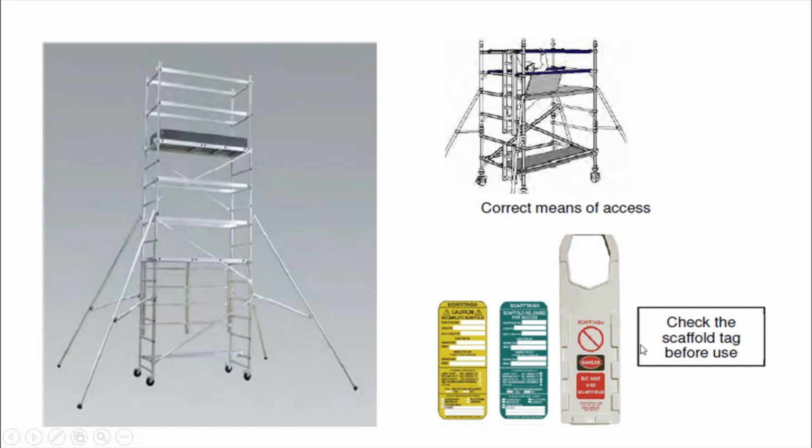And this is a sample of a scaffolding inspection tag. So you can see here what is the capacity of the scaffolding, and if this is on yellow, that means the scaffold is under erection or not yet completed, or sometimes they cannot complete because of the presence of structures like the pipes. So you need to have extra care while using the same scaffold.